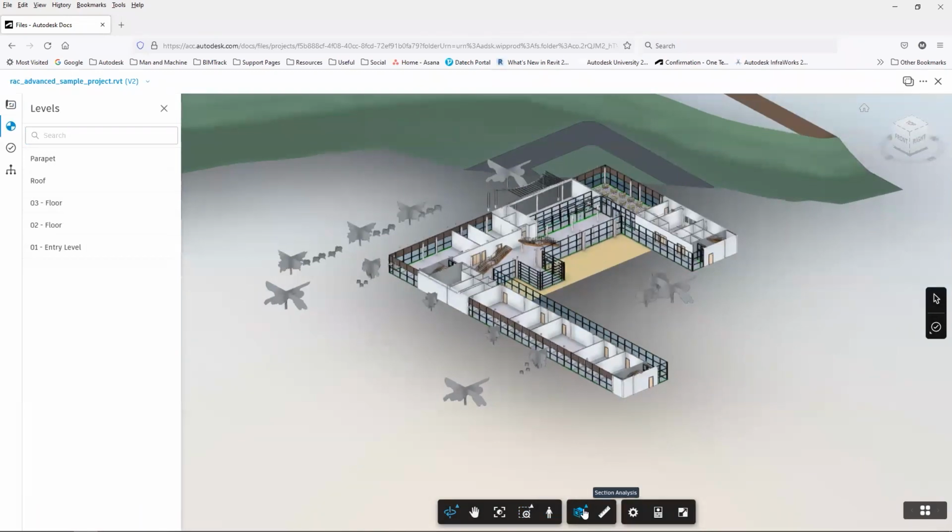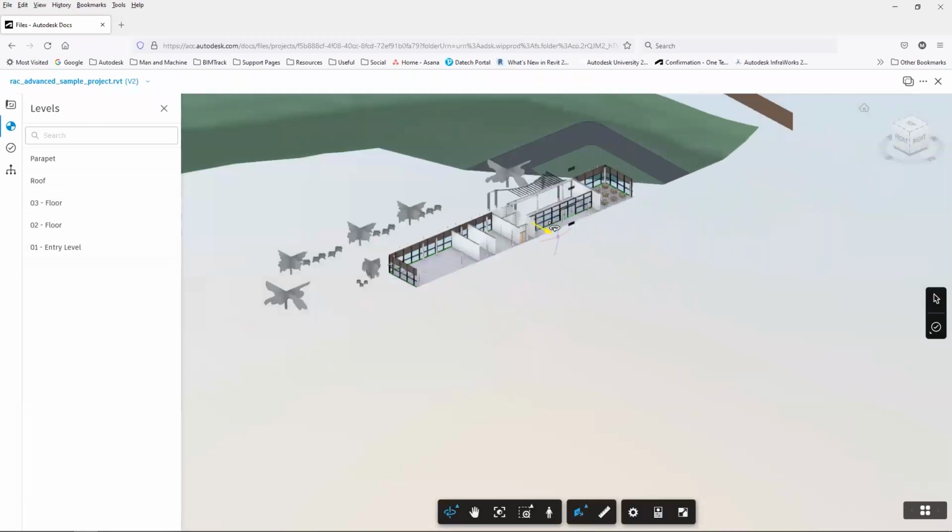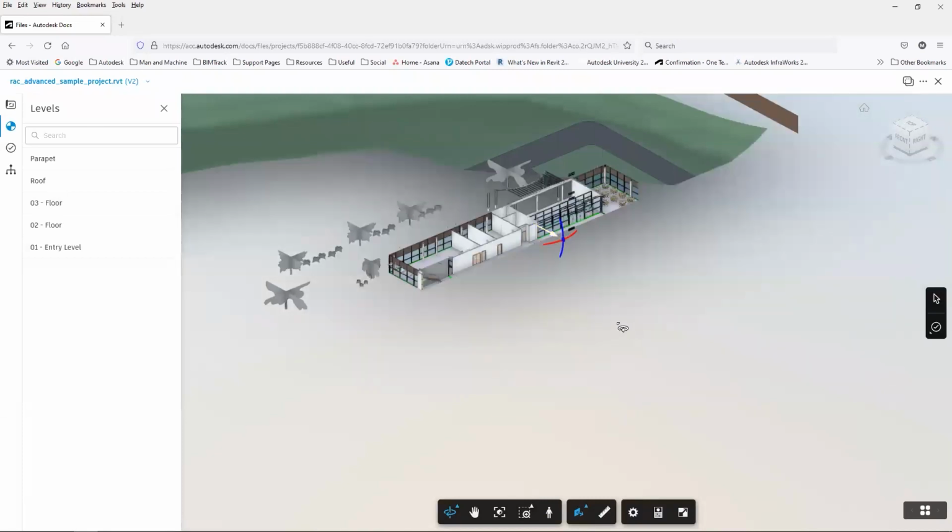And we have our section tool here. You can add a box section, so you get all 6 planes that you can manually adjust and crop. Or you can add planes onto specific axes. Again, you get this little widget here, and we can drag that through the model, and we can crop it to the extent that we want to crop that down to.